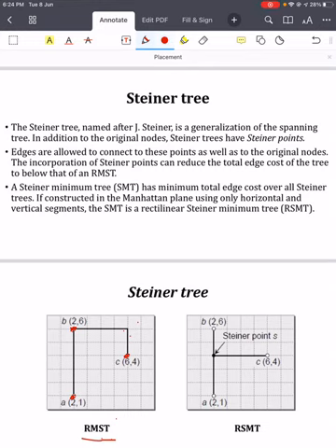Okay, now here in the Steiner tree we can have the branching at any point, and we will do this branching because our objective is to minimize the wire length. So here we are doing this branching. So here we have connected A and B. So the same branch is there here also, right? But we are taking a Steiner point.